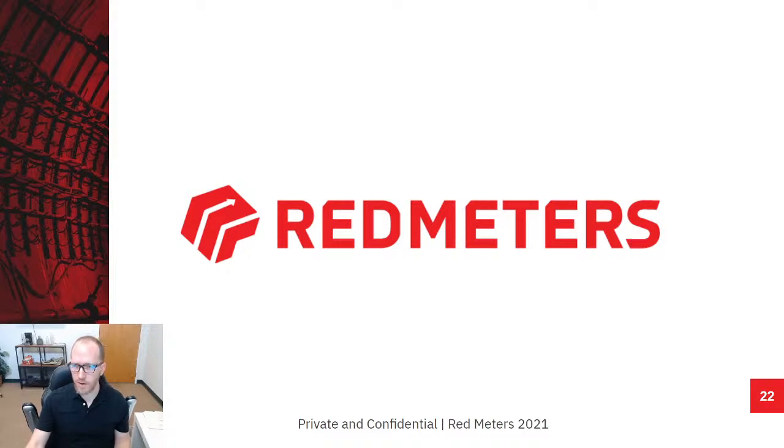Output types, that's another big question that we get. So we have 2 channels of 4-to-20 milliamps, and we have Modbus over TCP/IP. There is also the ability to just export the raw values in a CSV format. So it'll look like an Excel spreadsheet, basically, with timestamps and all the raw values that correspond to those timestamps.